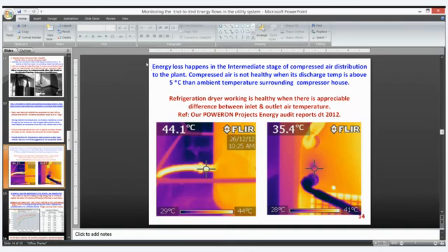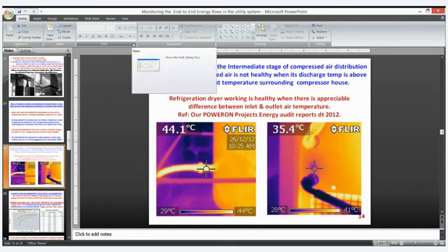See, these are all the intermediate power transmission losses. They are energy influencing parameters, not direct power, but if the parameters are not healthy, then the pressure drop is more. It has been suggested that for every 1 bar, almost 6 to 8% power loss happens. The power becomes high.